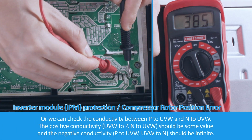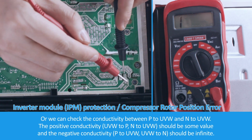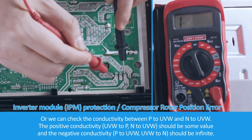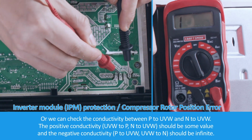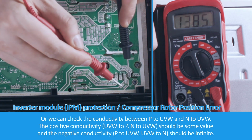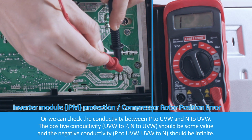Or we can check the conductivity between P to UVW and N to UVW. The positive conductivity UVW to P, N to UVW should be some value, and the negative conductivity P to UVW, UVW to N should be infinite.